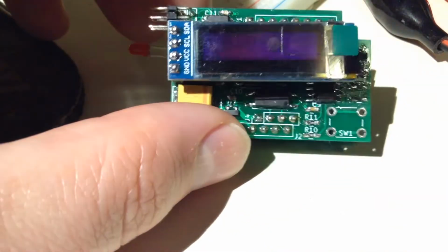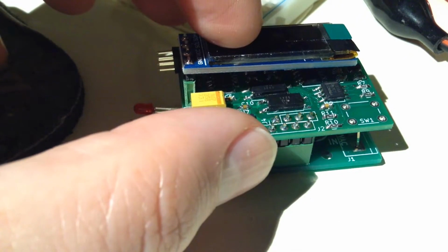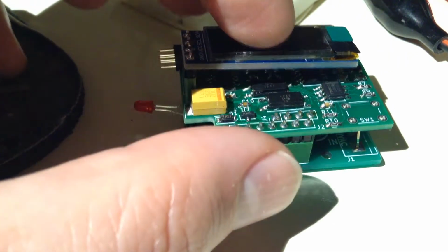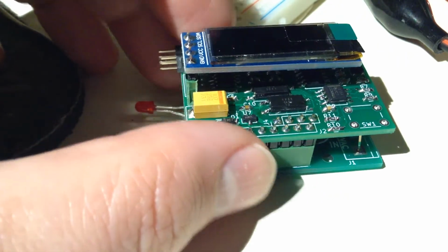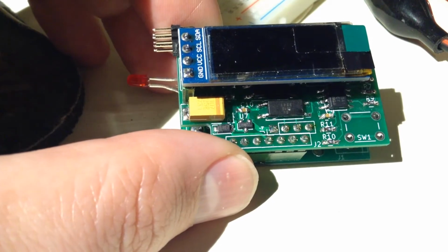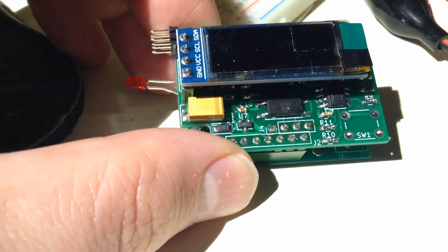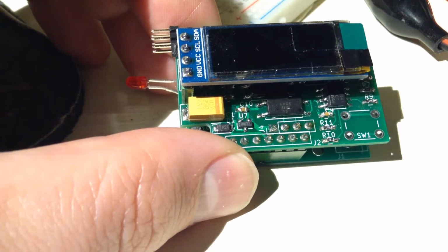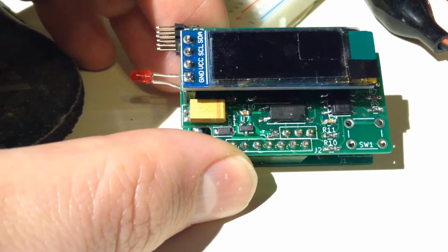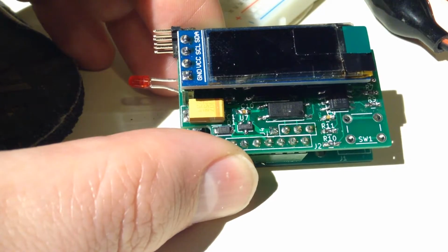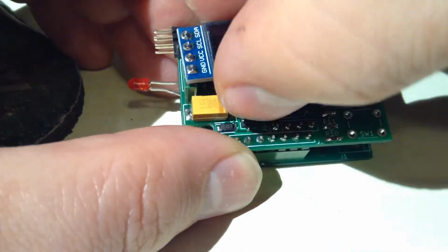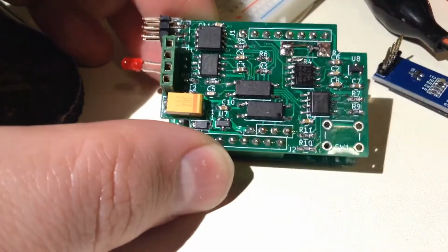And then you have a button on the side, so you can control it. You're supposed to see voltage, current, and a menu. In the menu you're supposed to also be able to configure it to cut off at a certain current. For example, if you wanted to cut at 1.5 amperes, you can set that, because we have instrumentation here.